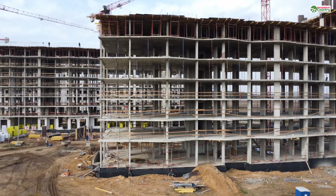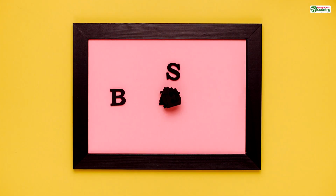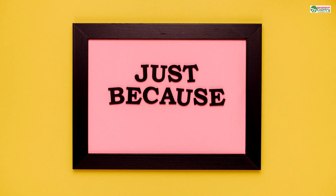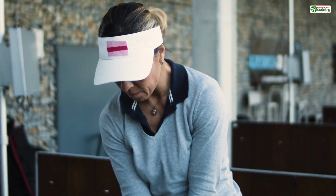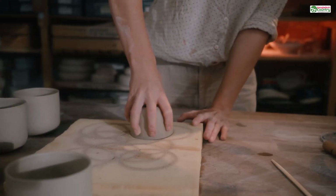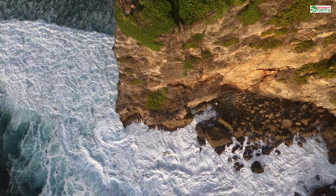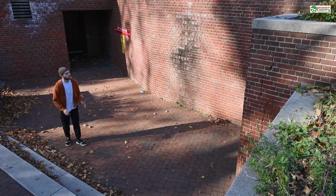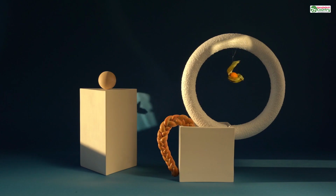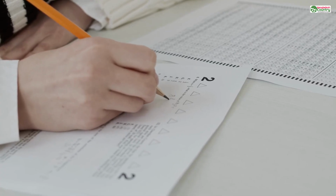If you're designing a miniature figure for a tabletop game, decide if it's a 28mm scale or a 32mm scale. Use a reference model of that size right in your scene. This practice not only prevents scaling errors, but it also makes you a better designer. It forces you to consider the real-world implications of your design choices. Will this wall be too thin to print? Is this hole big enough for a screw to pass through? You can only answer these questions if you're working with accurate, real-world numbers from the start.